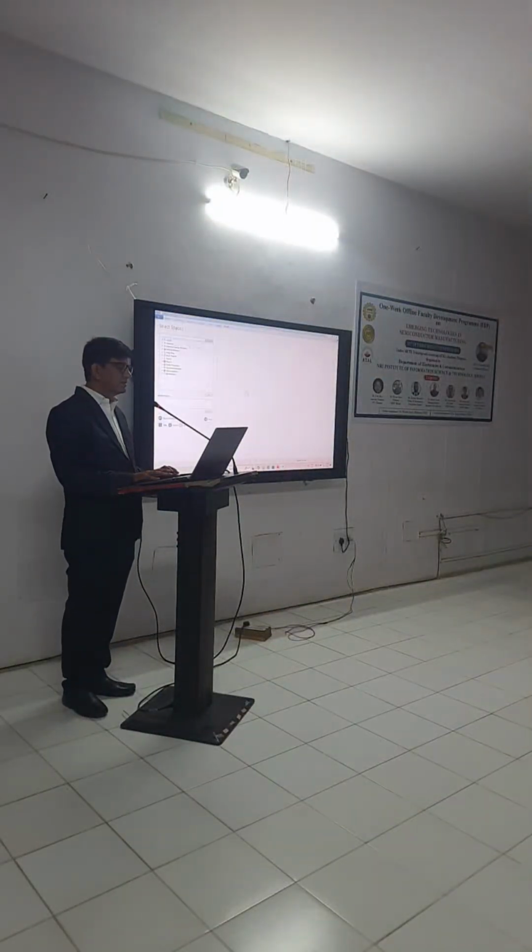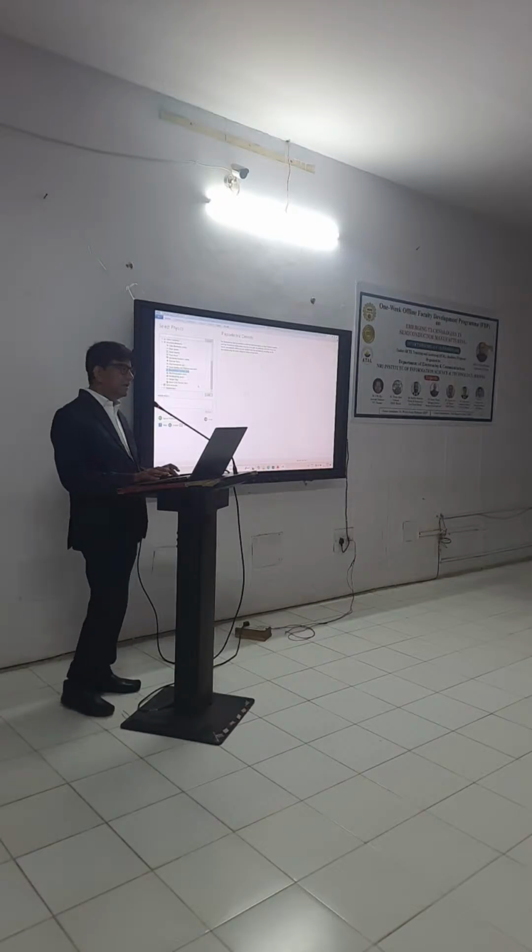So we will click on this, and then we have to select physics. What kind of physics do we require for our device? Let's suppose we require structural mechanics, and in structural we require a piezoelectric device, because we want to find out the analysis for my acoustic resonance. For that I need structural mechanics, and in that I need a piezoelectric device. So I will select that piezoelectric device, and I will add this as a physics.